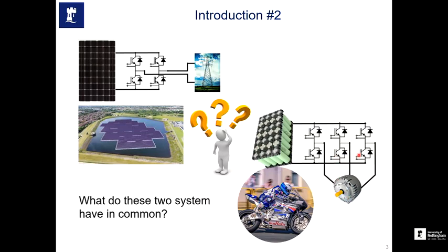And for the AC voltage generated at the output of this three-phase inverter, there will be a phase shift. It is a standard three-phase system, so the three voltages will have a 120-degree phase shift, which you can achieve by using the proper modulation technique for the three-phase bridge utilized in this inverter.